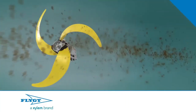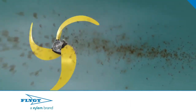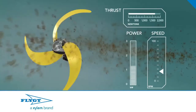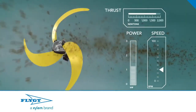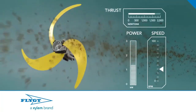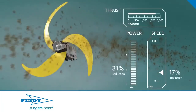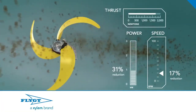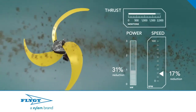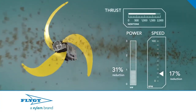A new world of possibilities opens up when you move to a mixer with integrated variable speed control, like the Flygt 4320. First, the power consumption at any given speed drops dramatically, thanks to the high-efficiency permanent magnet IE4 motor, combined with the mixing intensity optimized for the actual operating conditions, using integrated variable speed technology. Second, watch what happens when the mixer starts slowing down to meet the actual needs in the tank. Small reductions in speed and thrust come with much larger reductions in power. These reductions in power and speed also can extend the life of the mixer and the intervals between servicing.